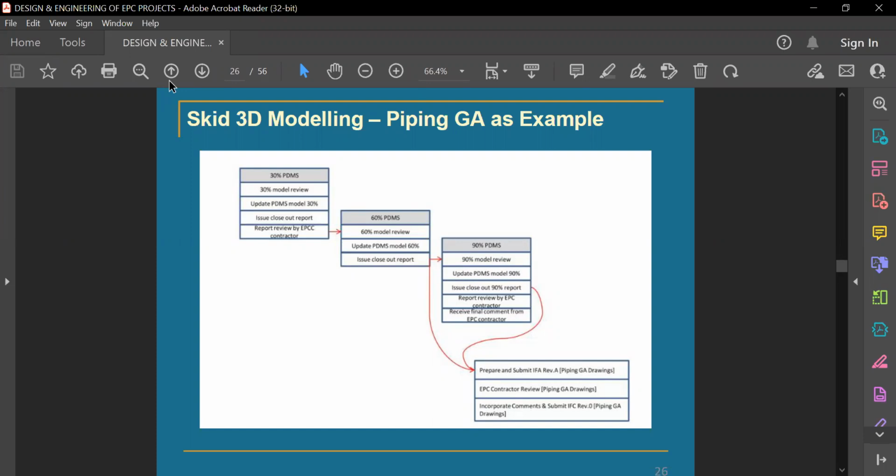It will be very congested, but at the same time we should have accessibility and stairs, and every cable and every pipeline should be routed, underground and above ground. For example, a trench shown by electrical people should not fall on the foundation of a pillar, and the pillar's foundation will be deep in the soil.